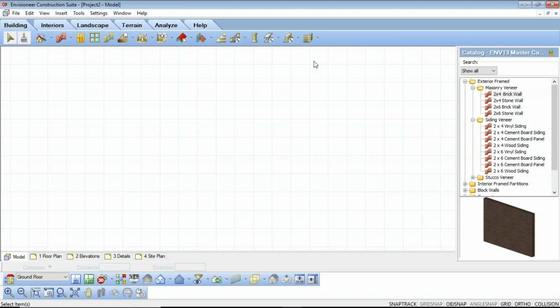First, you want to look at drawing walls to exact dimensions. When you know the exact dimensions that you want your perimeter walls to have, you can use the Walls by Baseline tool. This option allows you to type in a precise length for each wall. As you draw your wall segments, a self-closing polyline diagram is formed. When you have finished specifying your wall lengths, you are then prompted to specify an offset method for those walls relative to the baseline that you drew. You can offset them from the outer face of the veneer, the outer face of the core, or the interface of the wall core stud.